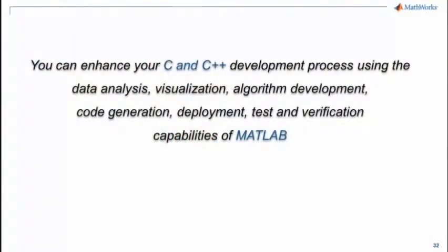Okay, so to summarize what I have tried to cover in this presentation, it's about how you can extend what you do within C and C++ at the moment, if you're using them as your primary development language, and how MATLAB can extend that for data visualization, using the engine interface to visualize what is going on, to help you with algorithm development, using the built-in tools and libraries for developing signal processing algorithms, and some of the methods for generating C code directly from the algorithms you have developed inside MATLAB, so that you can package them in your C or C++ application or interface them with your other desktop applications.